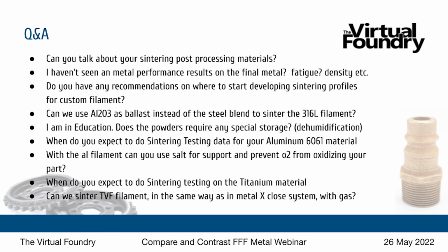Okay, Brad, the person who asked the question mentioned magic black powder. Matthew, let me tell you, forget about magic black powder. That was an early tool that we used in the debind and sintering process. It has been replaced with dry powders that are much easier to use. It was sort of version 1 of what we now do with the ballast and the Al2O3. It was inconvenient, difficult to work with, and it's over.